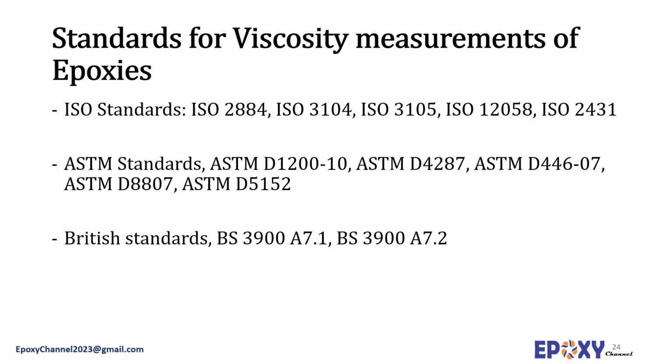ISO 3105 gives specification and operation instruction for glass capillary viscometer, widely used for the determination of kinematic viscosity of petroleum products. ISO 12058 is based on the falling ball method. ISO 2431 is based on flow cup measurements.